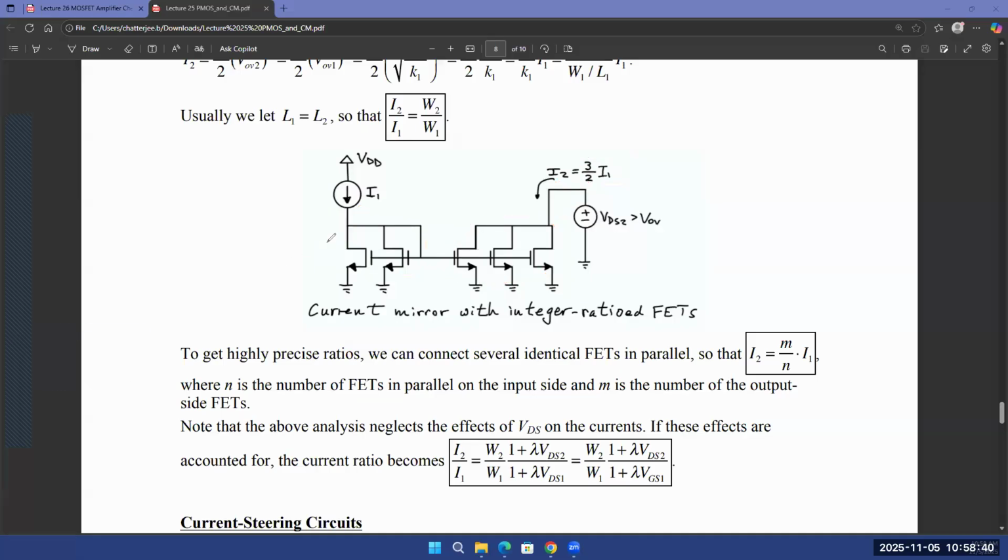And then if your technology node allows you to have any width, this is assuming that the transistors are kind of like a black box. You are not able to change the width or length of the transistor, so you just put transistors in parallel or in series to change the effective width or effective length. The technology might also allow you to have any W possible. Okay, I'll choose the W of this transistor to be 100 nanometer, and the W of this transistor to be 110 nanometer. Maybe the technology allows that. In that case, 100 and 110 will get added, and you'll effectively have 210 nanometer of width.